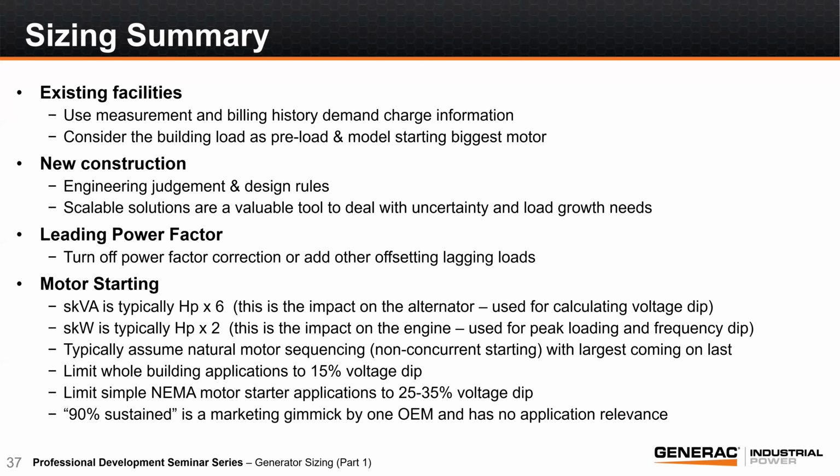Well, in all of the conversations that we have regarding this, make sure that you have a good quality fuel. So, if you're using pipeline natural gas, there's the assumption that you are using 1,000 BTU fuel. But if you know that this particular natural gas provider has some issues with their fuel quality, that's a conversation to have. If we switch to diesel fuel, and you're not taking care of your diesel fuel, there's a potential that the unit's not going to perform as well, right? The longer that you hold that diesel fuel in that tank, it's going to chemically break down. It may not give you the BTUs that you're expecting.